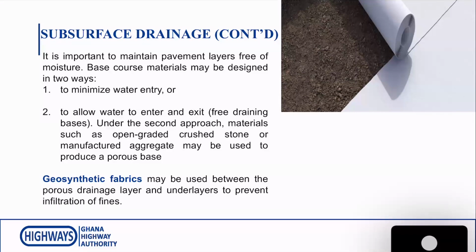Okay. Now, geosynthetic fabrics may also be used between the porous drainage layer and the under layers to prevent infiltration of fines.